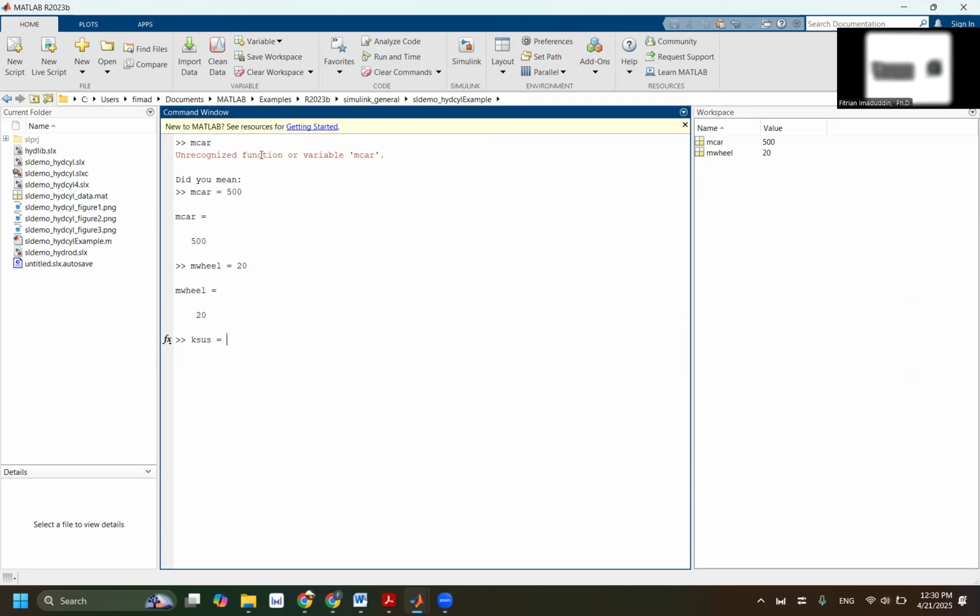So 100 kilogram multiplied by G, say 1,000 Newton, and 1,000 Newton is able to deflect the suspension by 1 centimeter. But your whole body, that 1,000 Newton, is actually supported by 4 suspension, right? So 1,000 Newton should be divided by 4 wheel, which is 250. This 250 Newton making deflection of 1 centimeter. So what is the K?